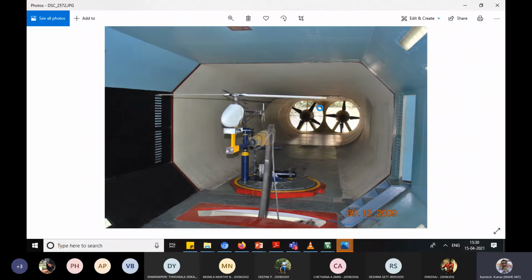What about the actual hardware when we manufacture it? We should go further, either in terms of structural testing or in terms of aerodynamic testing, correct? So aerodynamic testing is done in the wind tunnel. So you should have a model. In the wind tunnel models you should have sensors first, and it should check the cross section of the wind tunnel, correct?